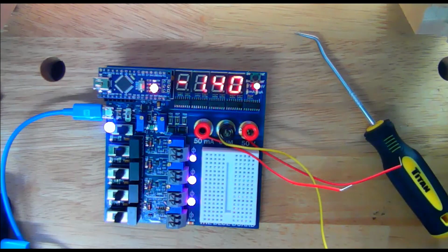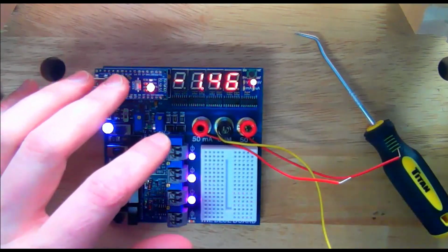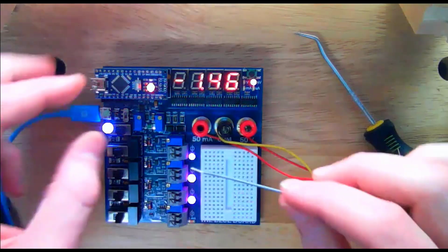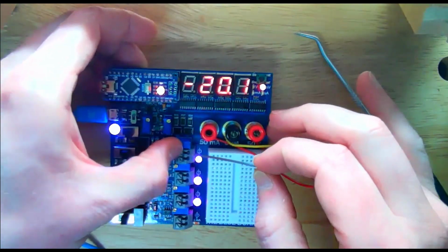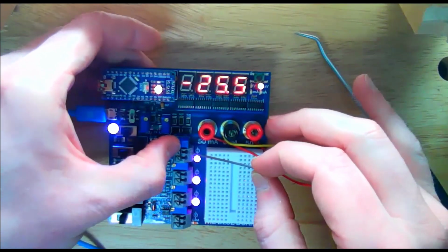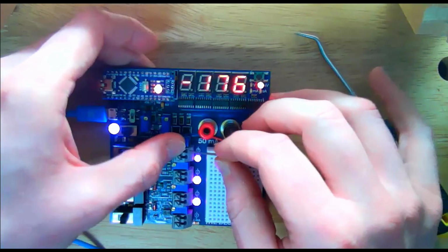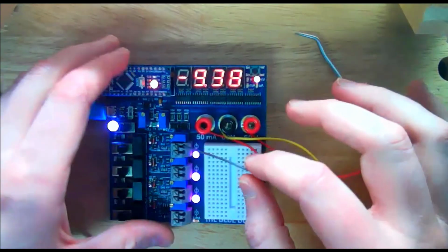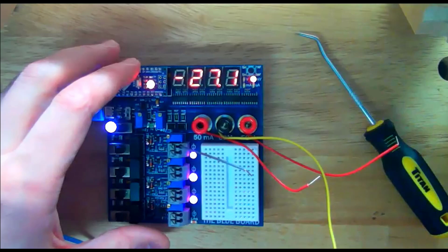All right, let's jump right into it. Connecting to these, let's measure a voltage first of all. Connecting to these voltage supplies is a simple matter of, you have spring terminals here. So you can depress the spring terminal and insert a wire, and I should be able to do it with my finger. These are kind of tough to push though. See how strong my nail is. Yeah, so you can depress that, and then once you've depressed that terminal, you can attach a wire, and it's spring loaded, so it'll hold that wire in place.